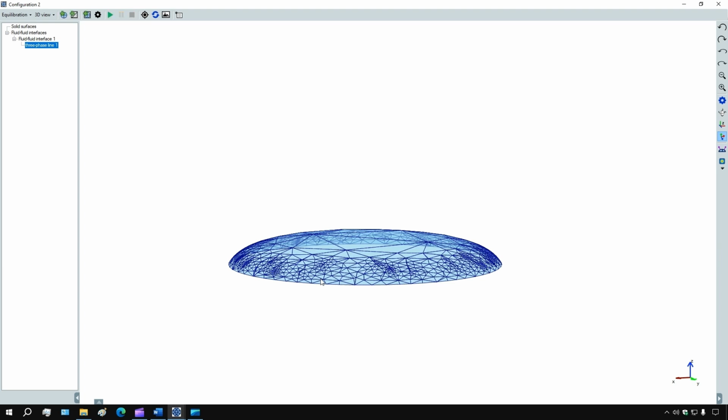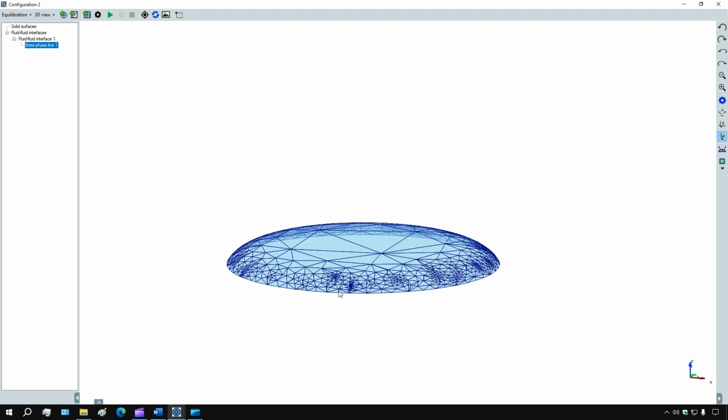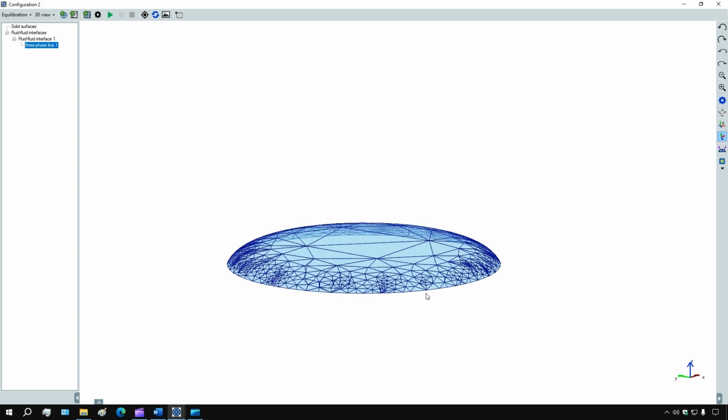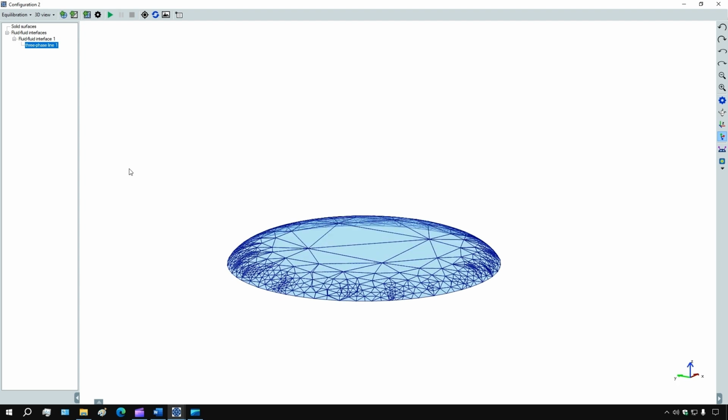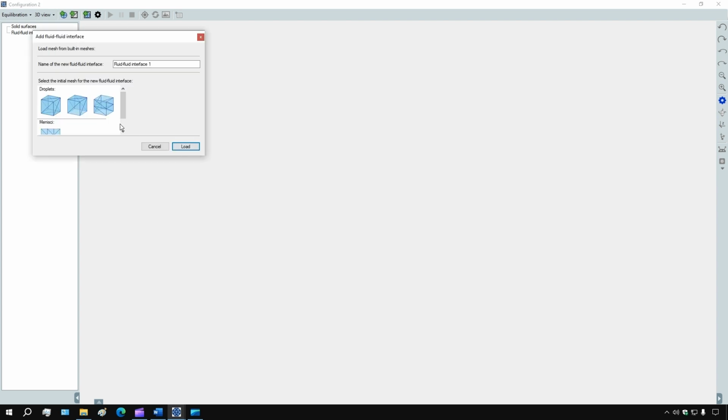The direction of the gravitational force field is opposite to that of the z-versor. Therefore, if we turn the sessile droplet upside down, we should obtain a pendant droplet. So let's try this. We consider again a droplet wetting a flat plane, but this time we will place it upside down. As volume for the droplet, let's set 80 cubic millimeters.